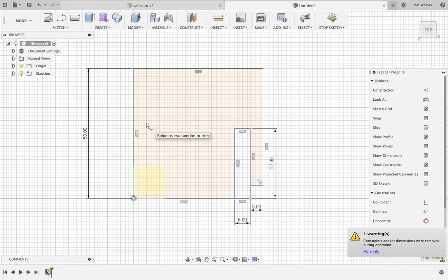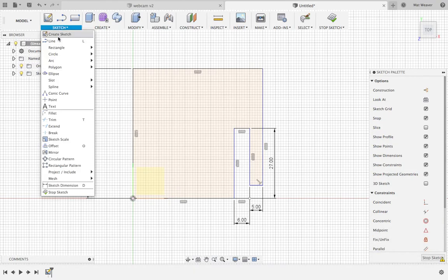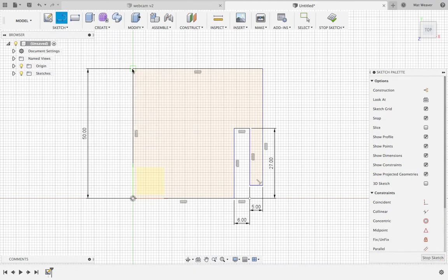Okay, the next part is a diagonal line. The diagonal line starts at 5 across. So, Sketch, Line, go in from there, go down to there, that's 5. Now I can actually see the green line again. So what I'm going to do is click once. Can you see the angles changing? Yeah. The angle, when it's there, is 90.